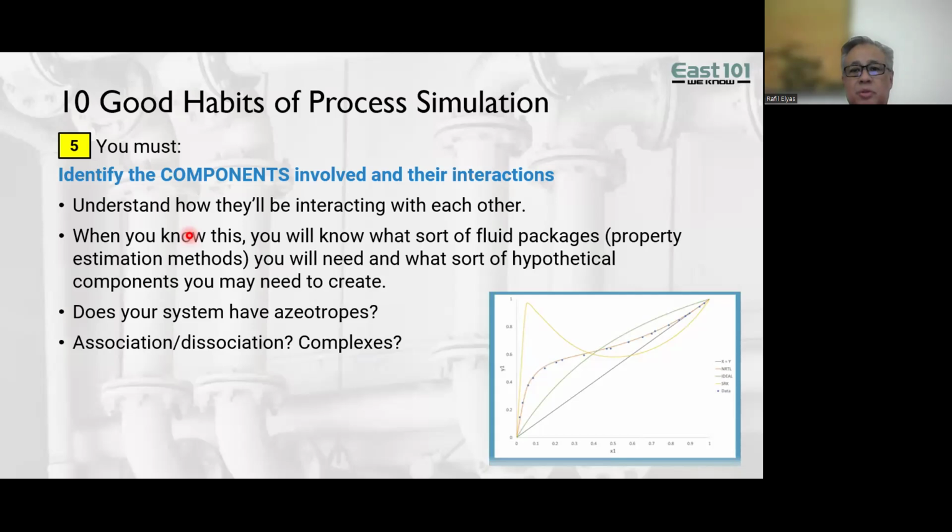I can't use these liquid activity coefficient models. Instead, if I'm using HYSYS or UniSim, I think nowadays they use CPA, cubic plus association models, to address this. In the old days, one would use HYSYS Peng-Robinson, because back in the old days, Peng-Robinson had all of this structure built in to represent hydrate suppression in the presence of methanol and glycols.